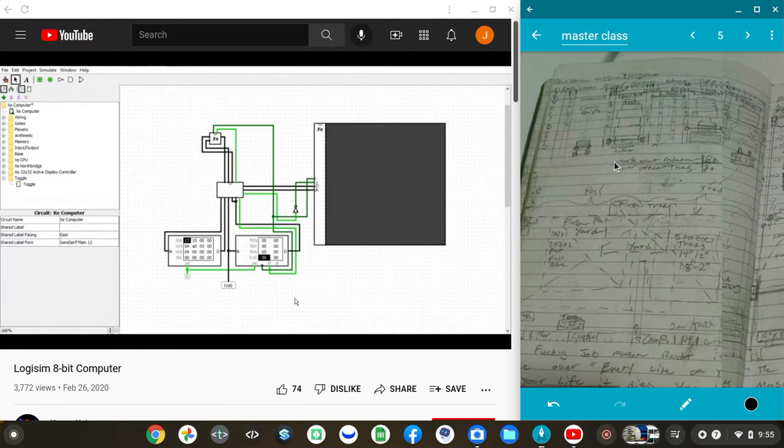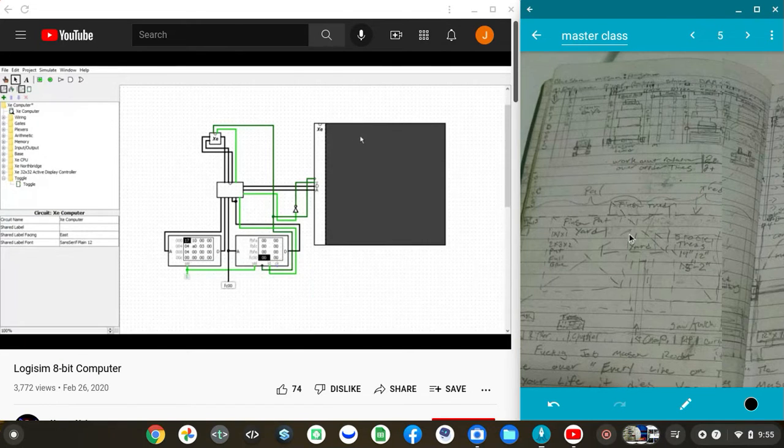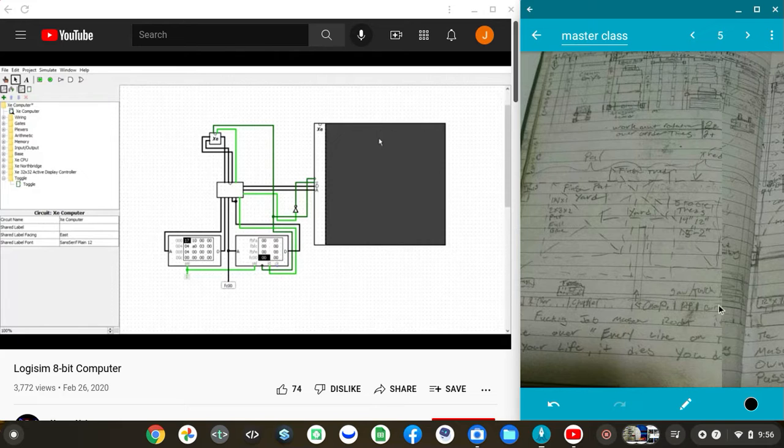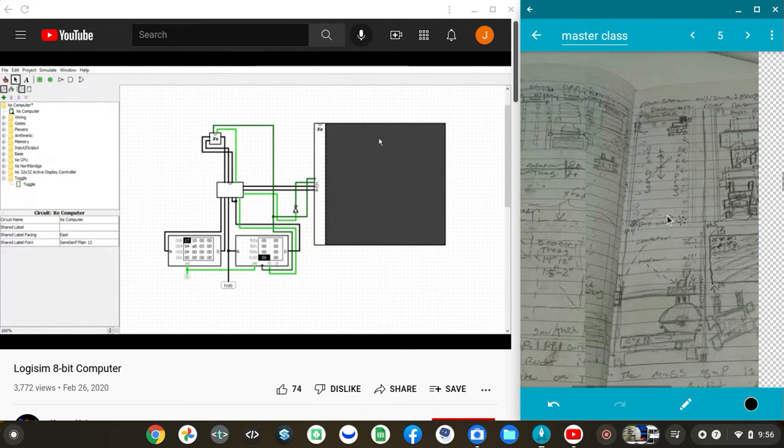So it should be fine, especially considering that this is a 1-bit LED matrix, I should say, because the lights can either be on or off, which means that it only takes up 128 bytes in memory. And that's a tiny portion of that whole 64K. And that means that stuff like sprites and graphics like that are also going to be really tiny. So it just works out in the end.